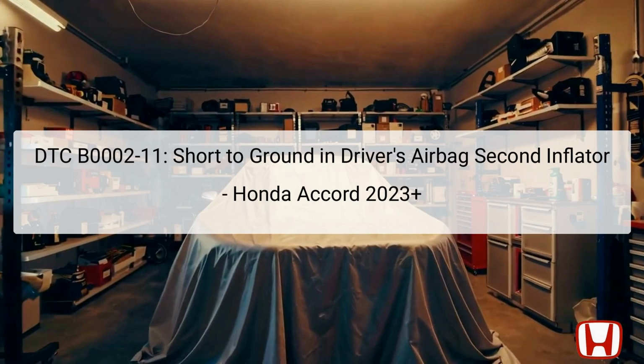The DTC code B0002-11 refers to a short-to-ground issue with the driver's airbag's second inflator in the Honda Accord from the 2023 model year onwards. This error signifies that the SRS, or Supplemental Restraint System, unit has detected an abnormal voltage or current on the detection line, leading to the storage of this diagnostic trouble code.